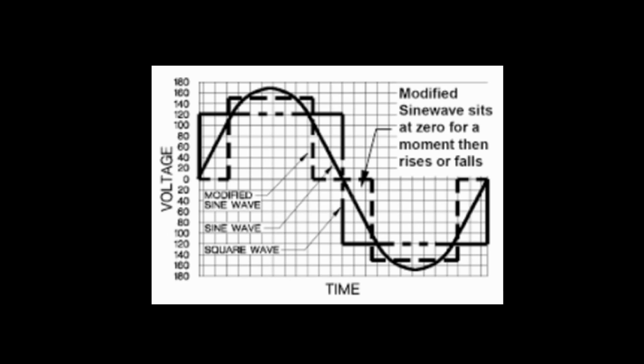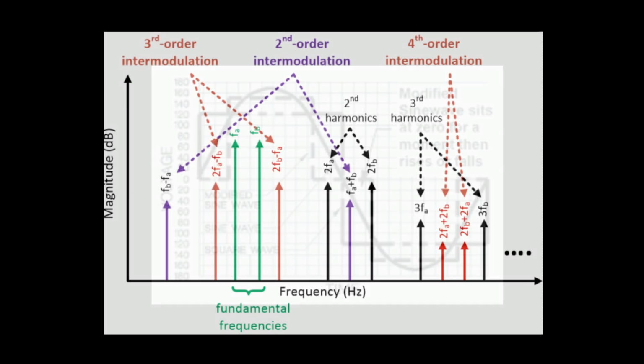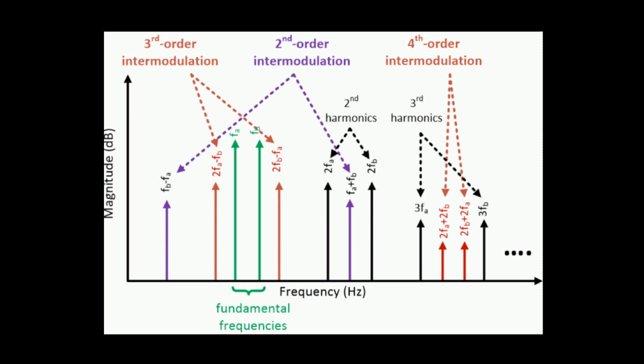So if we can get a near square wave into that LO, we're going to limit that intermittent period when the mixer diodes are partially open and partially shorted. And that's going to reduce the intermodulation distortion. I know it's kind of hard to see, but